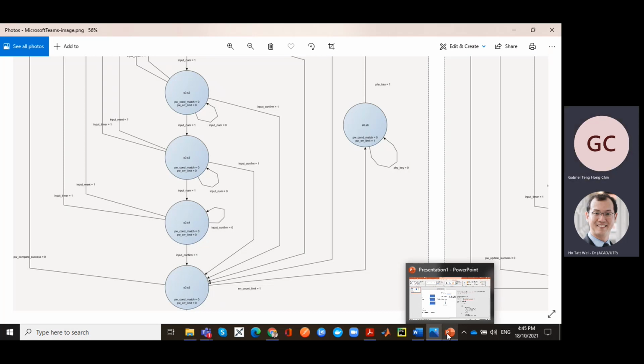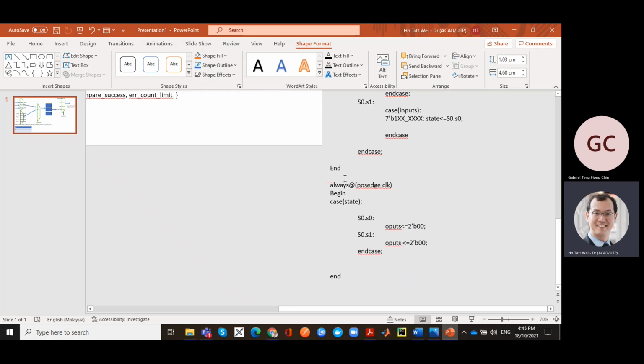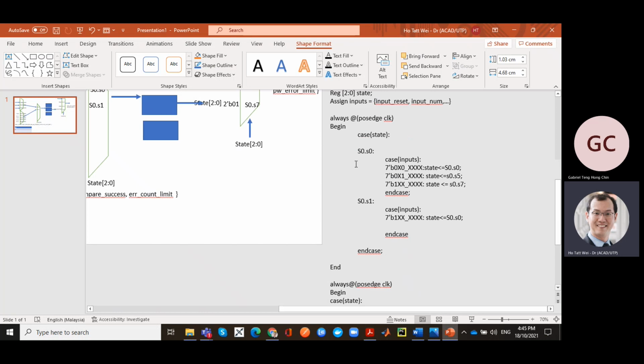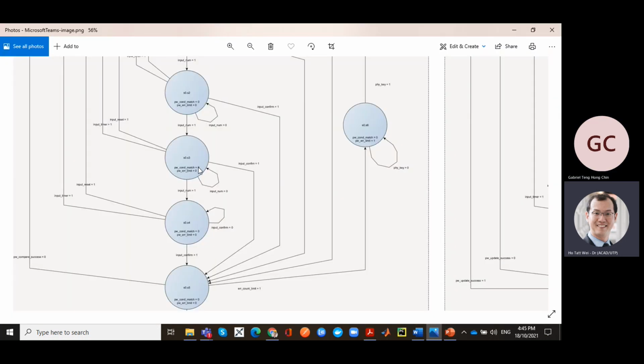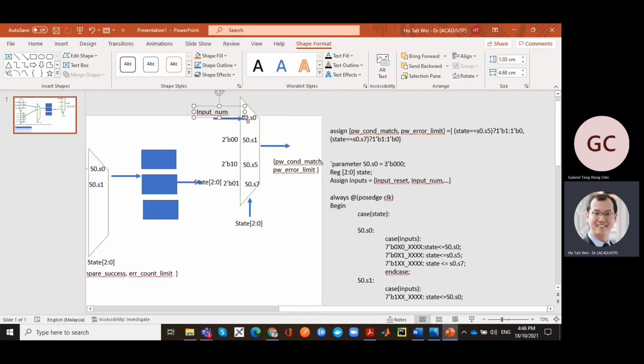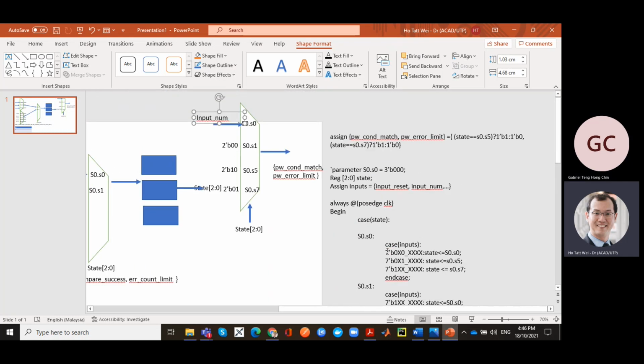Okay. So right now you've coded it as a Moore machine. This is no problem. You can go ahead and use this. It's probably going to be simpler to code out. But just remember, if you actually happen to encode a Mealy machine, which means your output is dependent on the transition, you have to take into account this particular transition. That will be those inputs that are also combining with the state to give you the output. And then it's not safe to use this coding. All right, great.